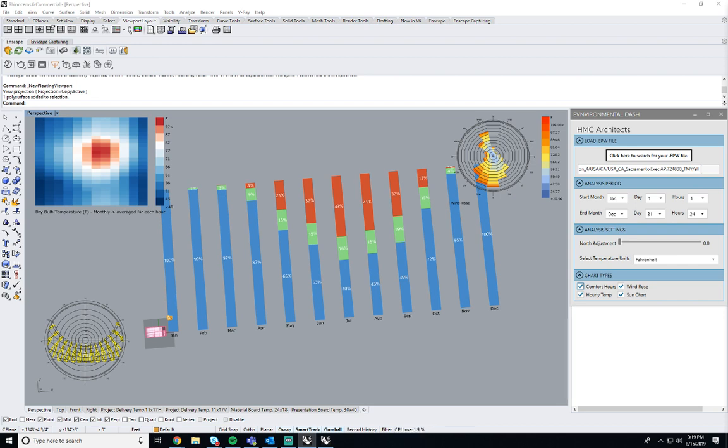So we've got to find the location first. Like we've done before, you want to pull out a render mesh to screen component, and then locate the mesh from the output. Plug that into the input, then add a point for the location, and add a scale factor so that we can accurately scale it to fit in the viewport.